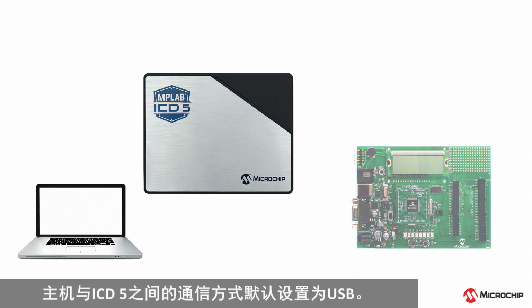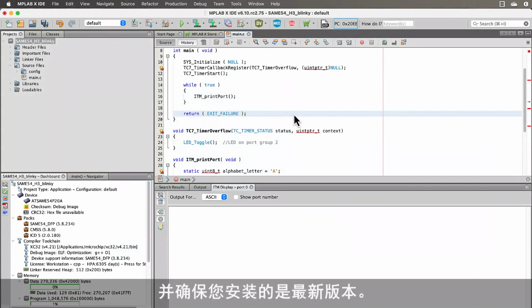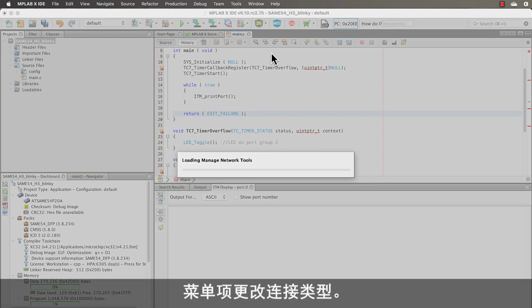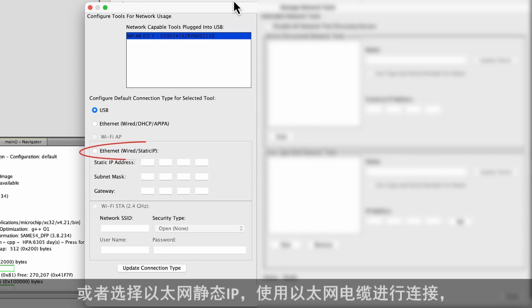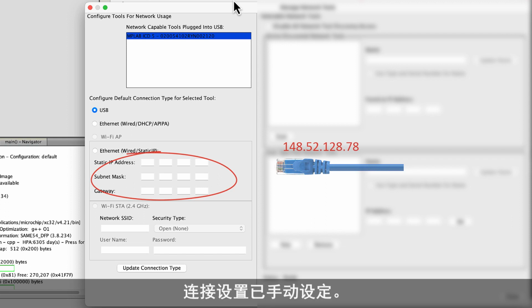Communication between the host computer and the ICD 5 defaults to USB. If Ethernet is preferred, run the MPLAB IDE, ensuring you have installed the latest version. Change the connection type by selecting the Manage Network Tools menu item. For the selected tool, choose Ethernet using DHCP to connect using an Ethernet cable and have IP addresses automatically assigned, or Ethernet static IP to connect using an Ethernet cable with connection settings that have been manually specified.